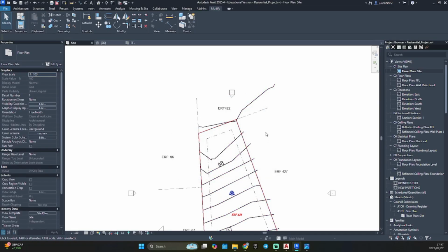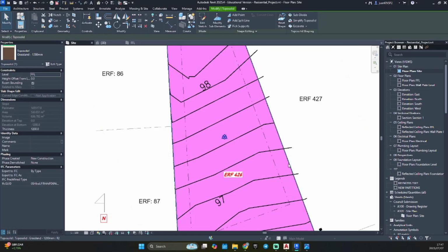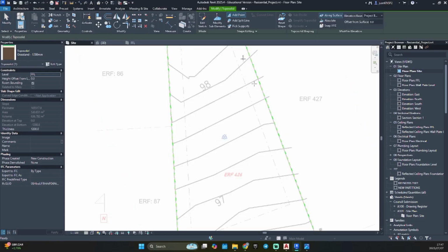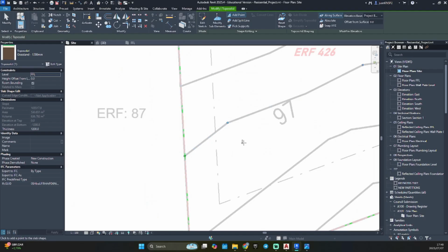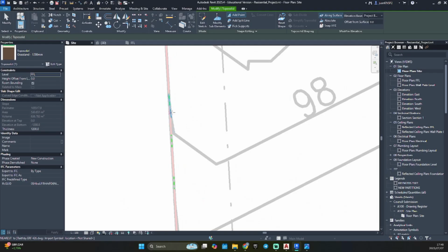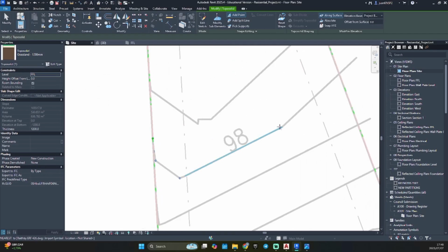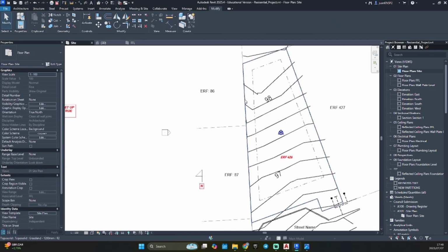Okay. So this is 1 meter. So let's start with 97. Select your topo solid, go Add Point. You can see now we can see those lines clearly. So let's add our points on our 97 meter mark and our 98 meter mark. So once we've added those, we can, apologies, I pressed Escape too many times.